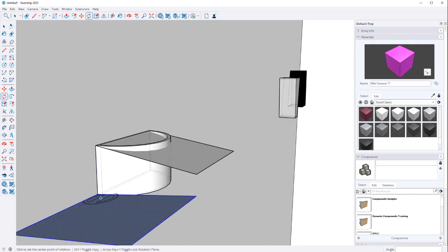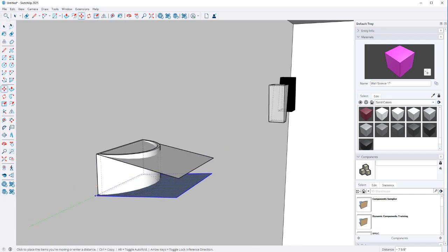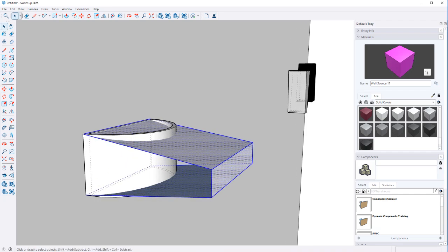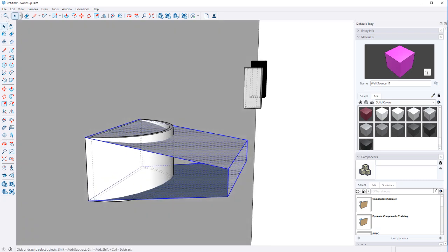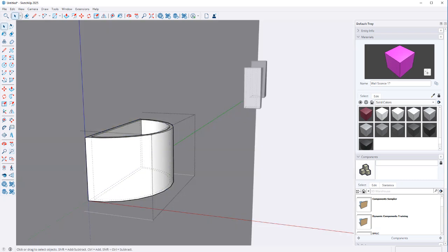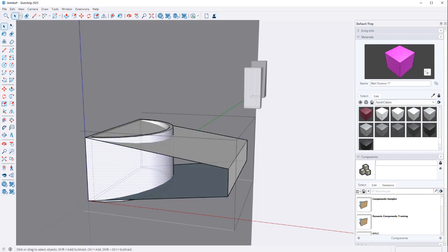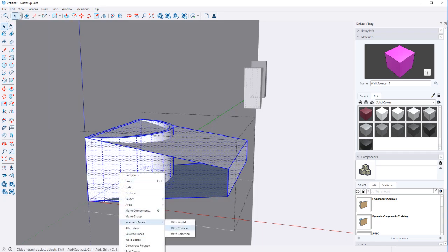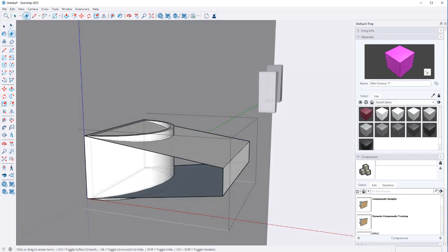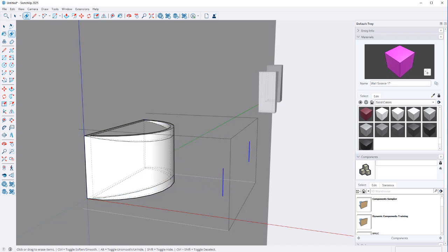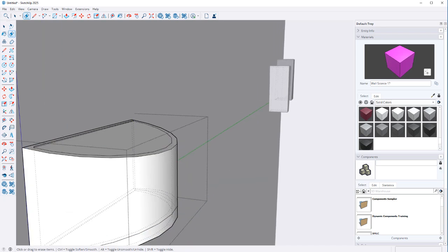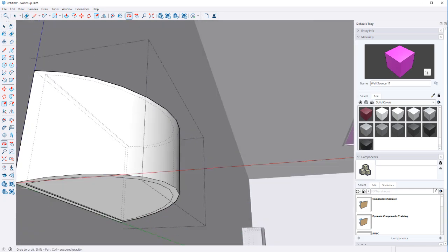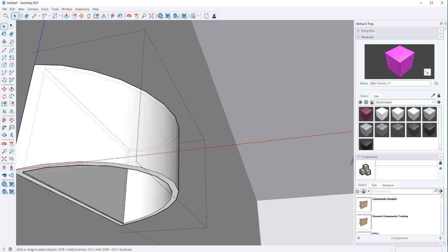We'll do 180, and then move this over, and then we'll just draw a rectangle so these connect. Slightly better chance of it working nicely that way. So then we'll cut that out, paste in place inside of here, intersect faces with selection, and now if we erase all this right here, we're left with the two faces right here, and then we have this space right here that we can cut away on both.